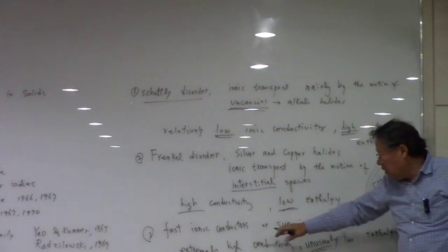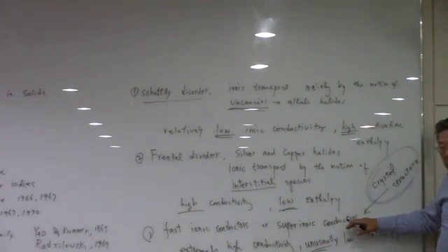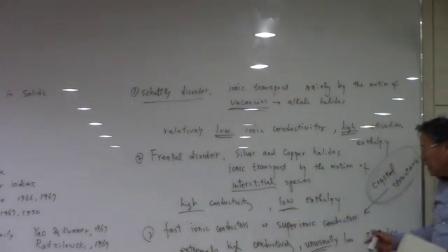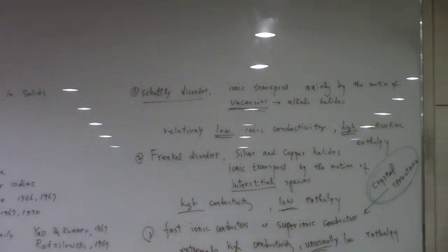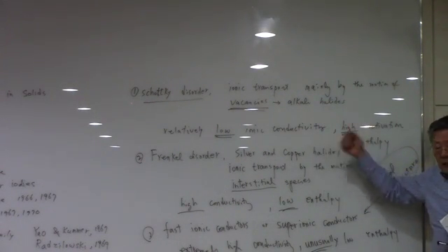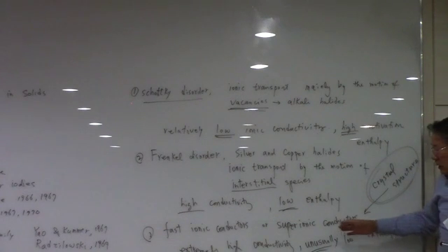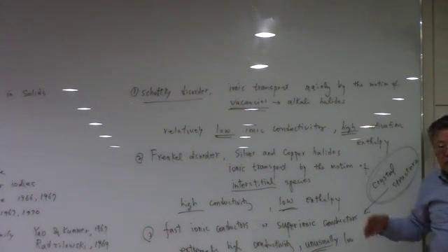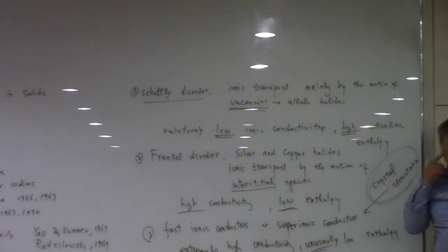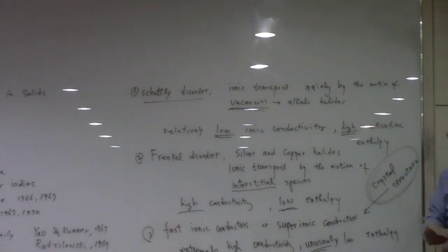But in a fast ionic conductor or the superionic conductors, it has a special crystal structure to show this unusually high conductivity. It is not really related to the defects that the materials have. Rather, it is related to the crystal structure itself to show the superionic conductors, like tunnel structures, layered structures, and things like that. Okay.